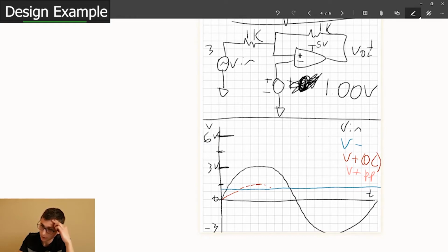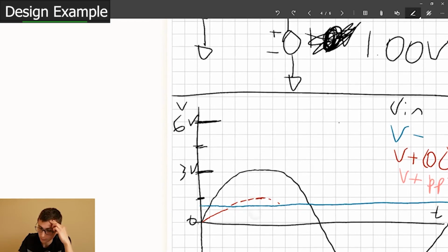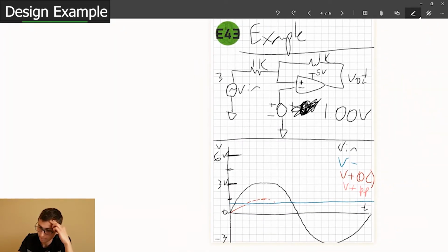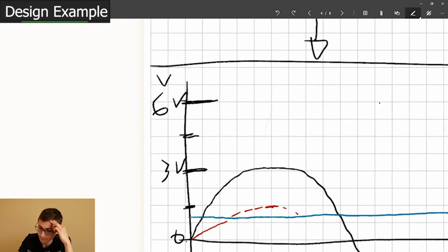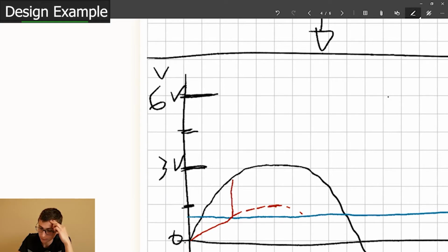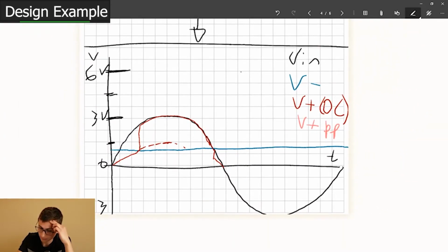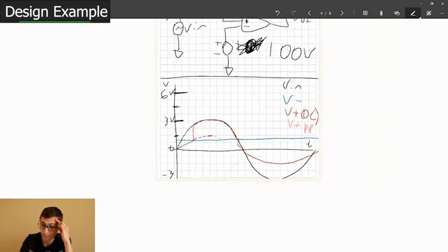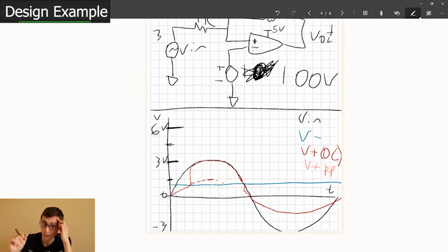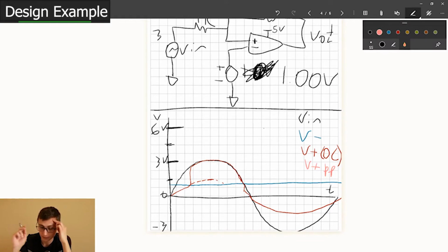for the open collector comparator, when this stops clamping to ground, we essentially remove this 1K resistor. And the waveform would snap up to, what is that? Vin. So basically we'd see this waveform have a discontinuity, jump up to Vin, and ride this wave all the way back down here, where it would then jump back down to being divided by 2. And it would finish out its life. And then, of course, it would just be, assuming we didn't blow anything up, half the waveform on the other side. That looks pretty interesting. Wow. Okay. But for the push-pull comparator, what is the difference?